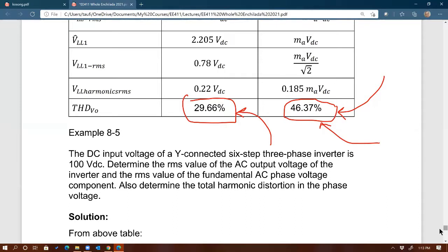Sorry, okay. I was muted. Okay, so by filtering it, you are blocking the harmonic frequencies to be present at the load. So you're blocking these frequencies. So then these frequencies are not present at all in the load, and so the load now is only absorbing the 60 hertz component, nothing else. So it's more efficient that way.